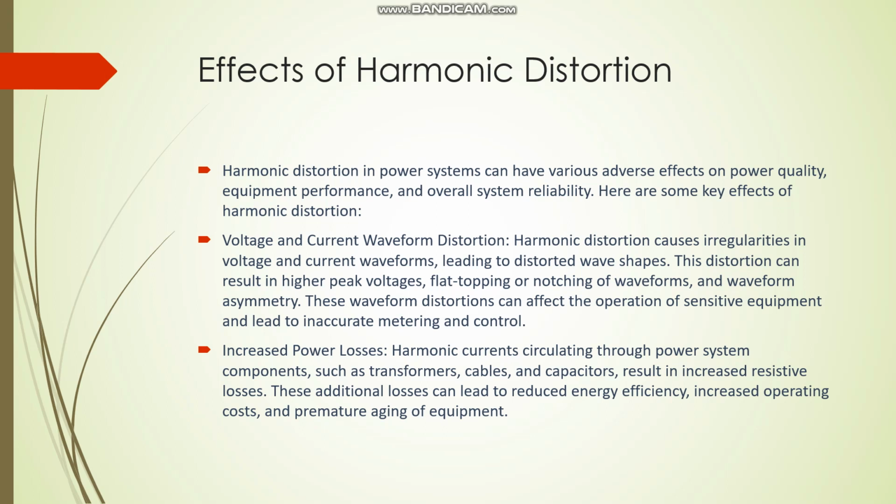Increased power losses. Harmonic currents circulating through power system components such as transformers, cables, and capacitors result in increased resistive losses. These additional losses can lead to reduced energy efficiency, increased operating costs, and premature aging of equipment.